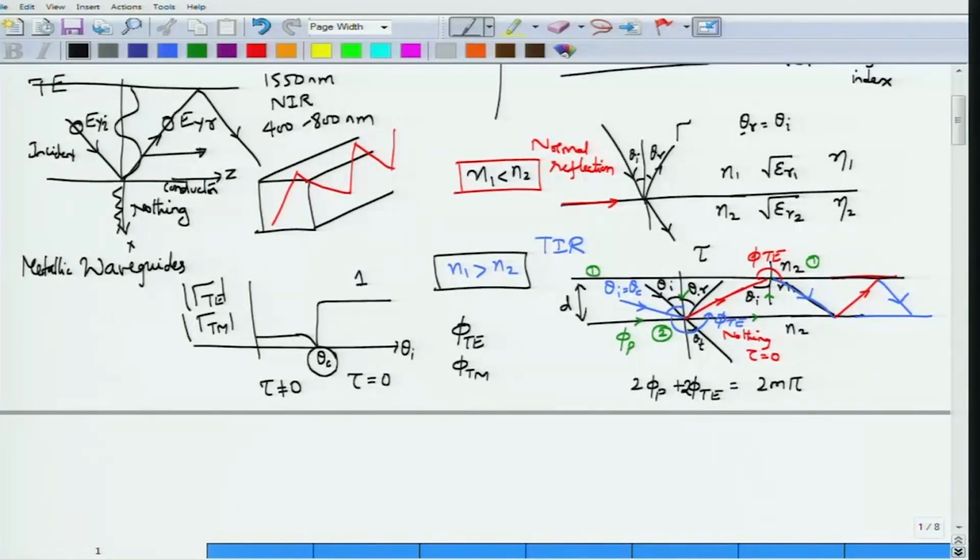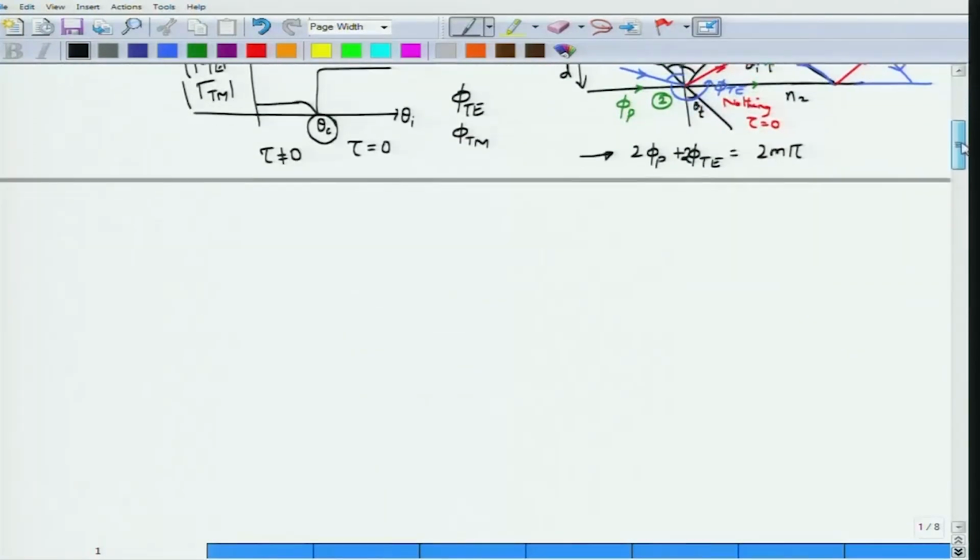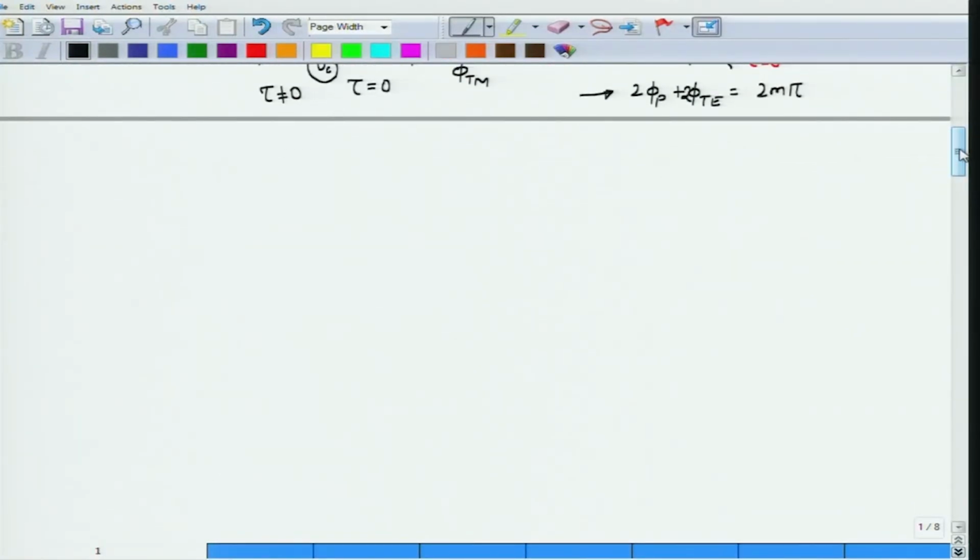Moreover, it must also satisfy this phase criterion, that the total propagation phase it has picked up over the distance propagated between two consecutive rays, plus any additional phase factor picked up because of the TE or TM mode description, must total an integral multiple of 2 pi. Okay. So, we start from this one and we will write the Maxwell equations to understand the mode shapes.